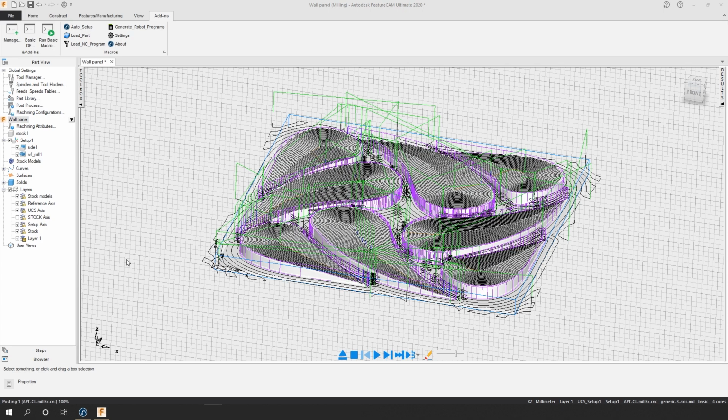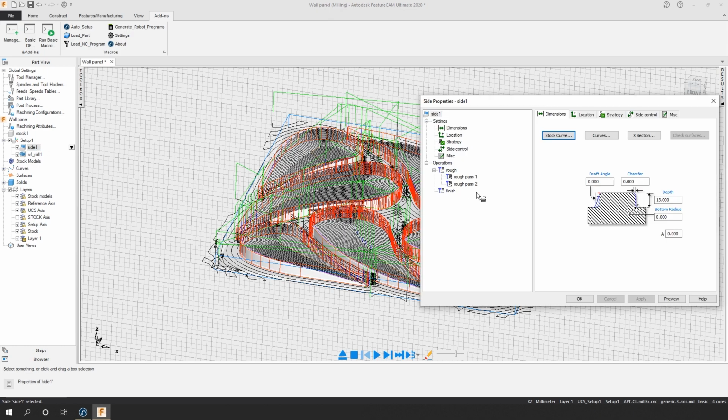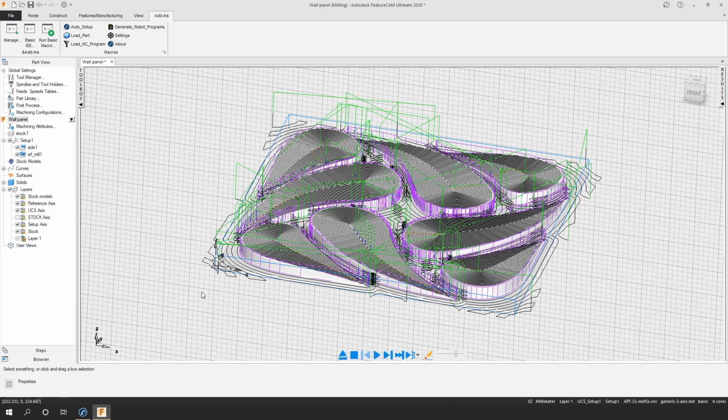This won't cancel the export of the path, just cancel the simulation in FeatureCAM. In this case, we should expect to have 3 programs in RoboDK. The one we imported before, so the surface milling, the roughing program for the general shapes, and the finishing program for the general shapes. Okay, perfect.